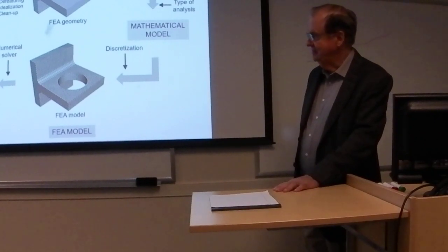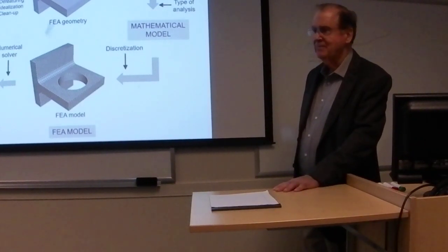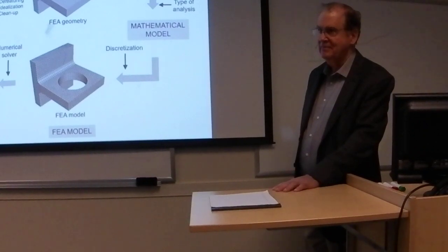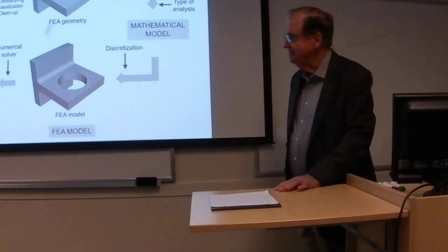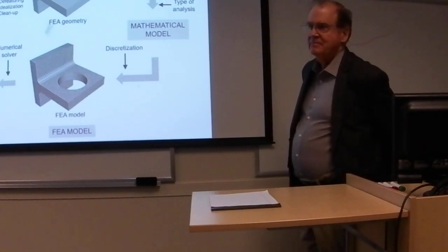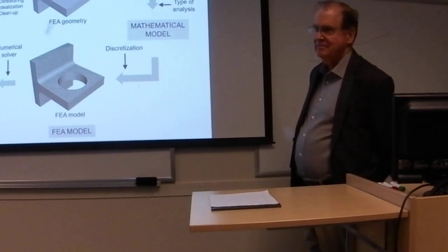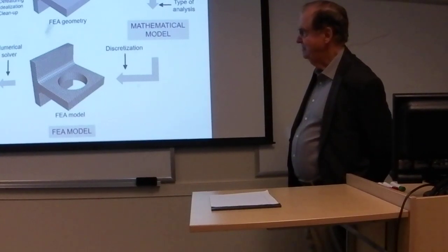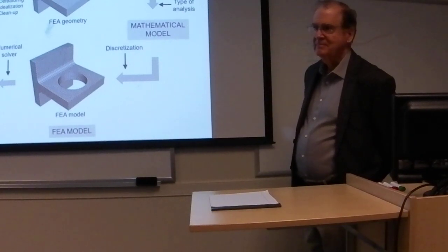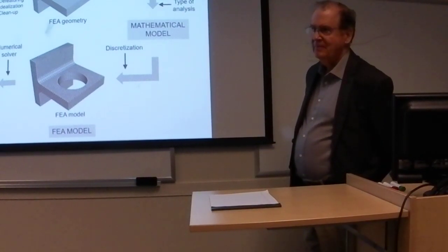Like the two red spots in there, those are actual errors in the visualization, which if you weren't aware of that or looking for that, then you would say, oh, that's the area of maximum stress. But having understood how the uncertainties and errors propagate up until that point, you can essentially eliminate that, truncate that data, something like that. So this was a huge point of the garnering of the uncertainties within the process, and the largest source of uncertainties come from the applying of the boundary conditions. Would you agree with that?